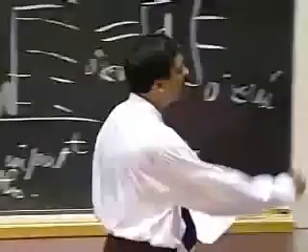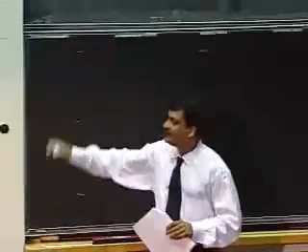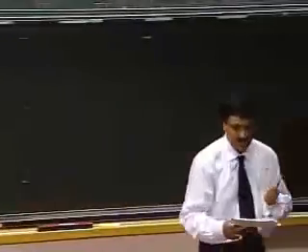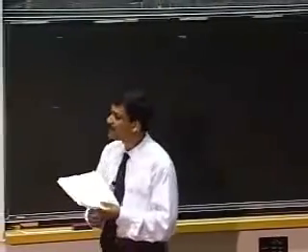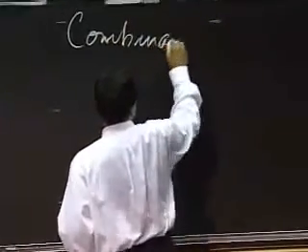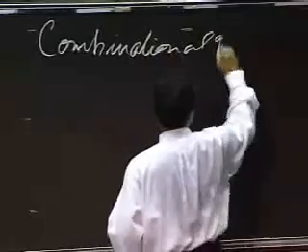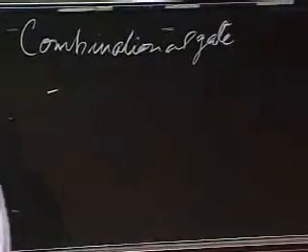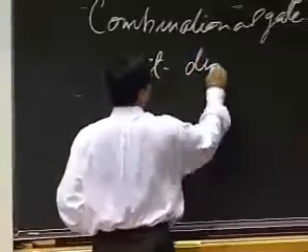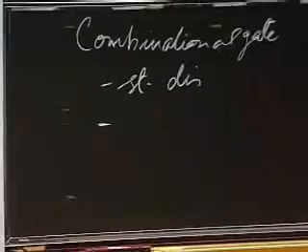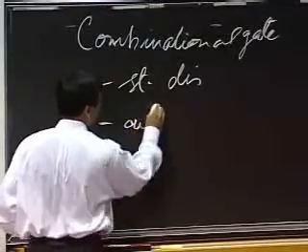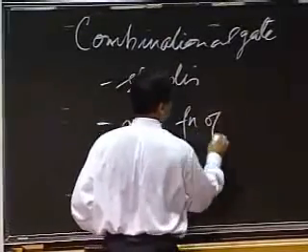Okay? So that leads us to, given this sort of voltage thresholds, we now move into the digital world. And in the digital world, we can build a bunch of digital devices. The first device we will look at is called a combinational gate. A combinational gate is a device that adheres to the static discipline, page 11. And this is a device whose outputs are a function of inputs alone.